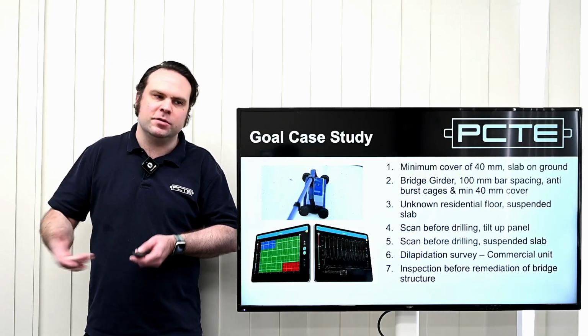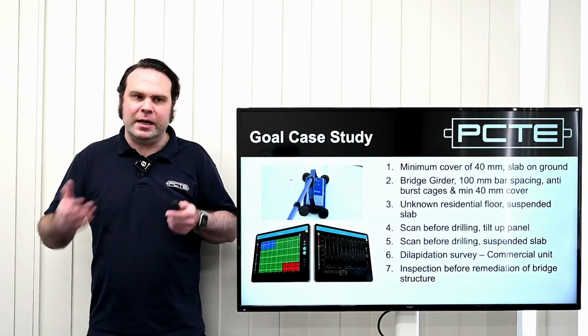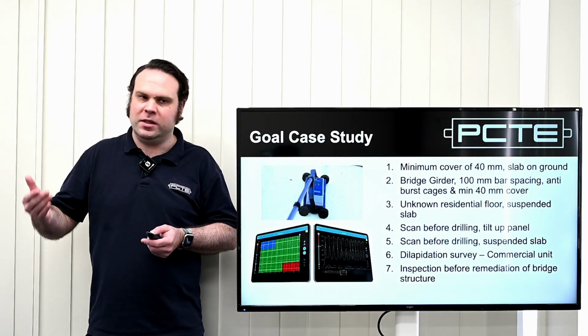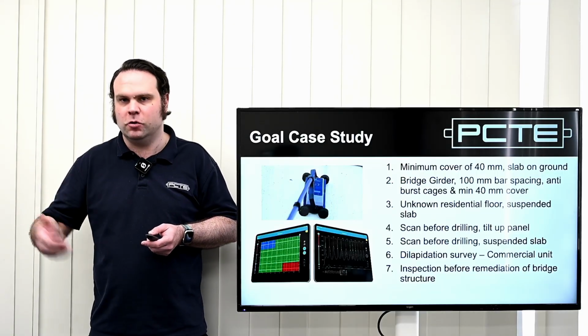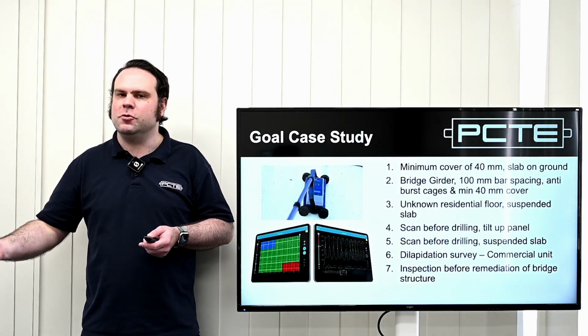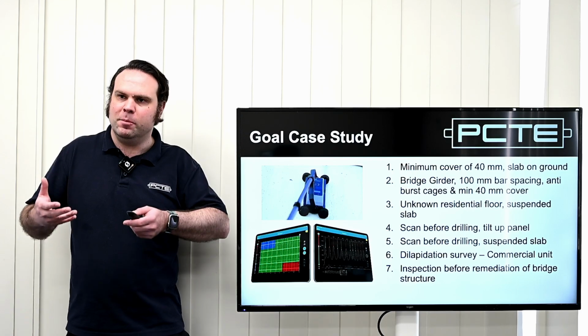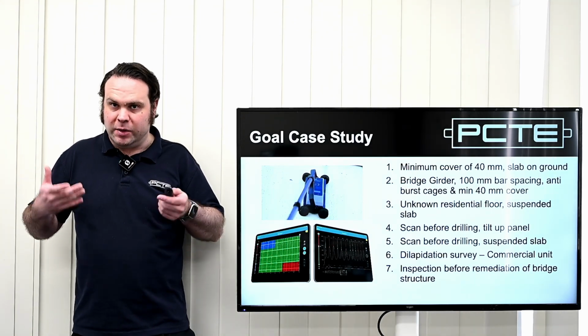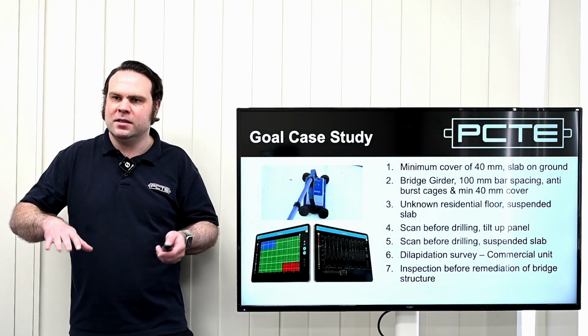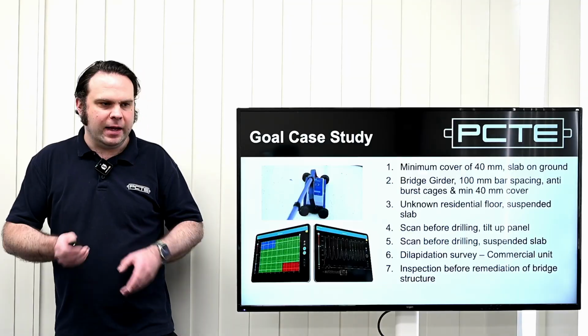So you would use a cover meter as one input on a durability survey, along with chemical analysis for carbonation and chloride depths, and then maybe some of your electrochemical corrosion methods. They form a set. Just doing cover alone isn't going to quite give you the whole picture. Okay, thank you.